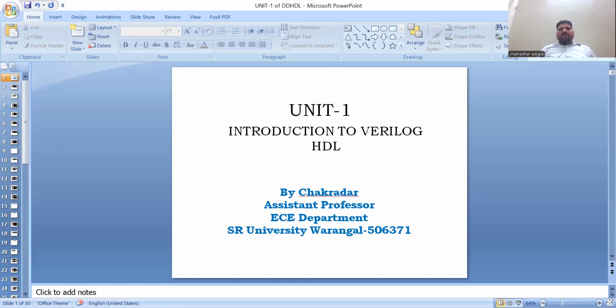Number specifications. There are two types of number specifications in Verilog, sized and unsized. This is used for the representation of different types of numbers. What we mention might be a binary number, hexadecimal, or decimal. So here comes the usage of sized or unsized numbers. Sized numbers are represented by the size before the base format and before the number.